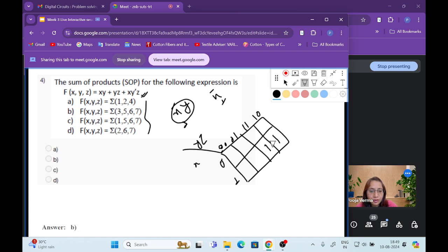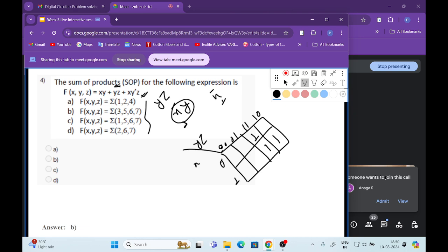So from this pair you will get only x and y. If you want to solve, you can solve it. So if you make a pair, then you will get from the corresponding row x only, and from here y only. So that means for the expression xy, or implicant xy, the corresponding cells will be 1, 1. Now we need to take another one. The other one is yz, right? Now how can we get yz from the K-map? So yz, that means in these four columns, any of them. But we need to check yz. So yz is only in this column, column number 3, right? So we just need to write it here. If you make a pair like this, you will get only y, z.